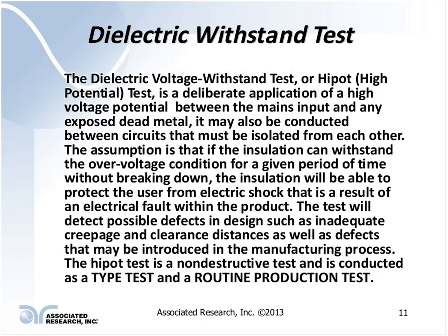It's assumed that if the insulation can withstand this higher voltage potential or over voltage potential for a given period of time without breaking down, the insulation should be able to withstand and protect the user of the product from any electrical shock hazards throughout the life cycle of the product itself.